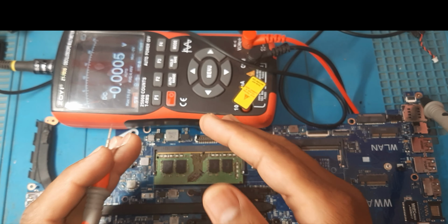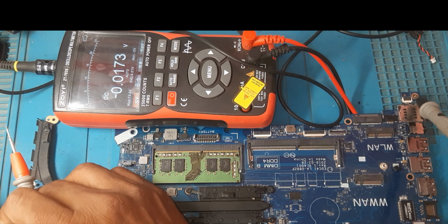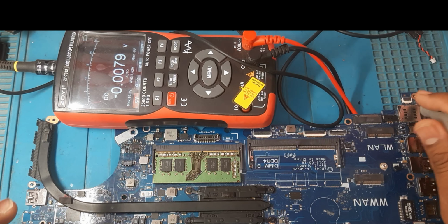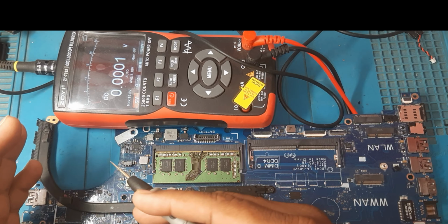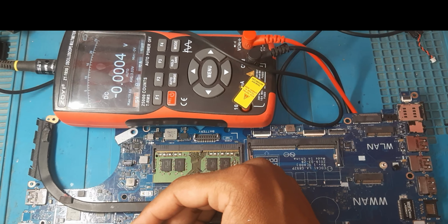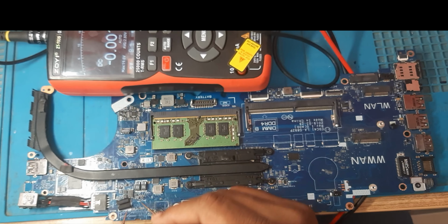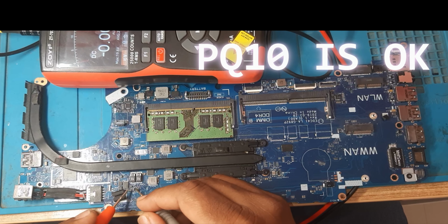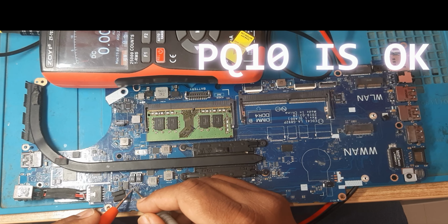What are the protection methods, the logic circuits of the protection? First we need to check them one by one. I'm disconnecting this. The gate we already checked, right? Now we need to check the MOSFETs one by one, to see whether any protection happened due to the overvoltage. The main thing, which I told you, is that the gate supply is connected to this 6-leg logic. Now we need to check first whether this one is shorted or not. Here to here, any pin: number 1 no, here no, number 2 no.